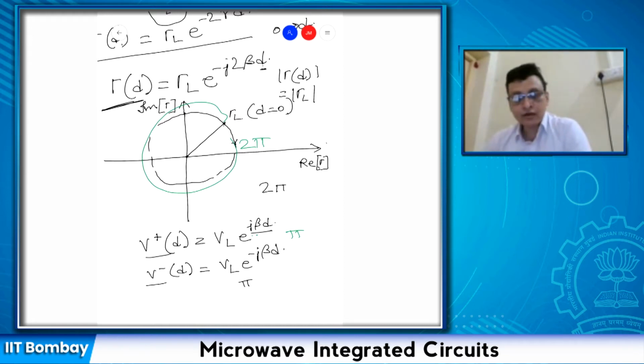So this is a very important aspect when we shall be discussing Smith chart, because it means that every change that we make in a transmission line has to be within pi phase change, and we saw that pi corresponds to lambda by 2 length change.